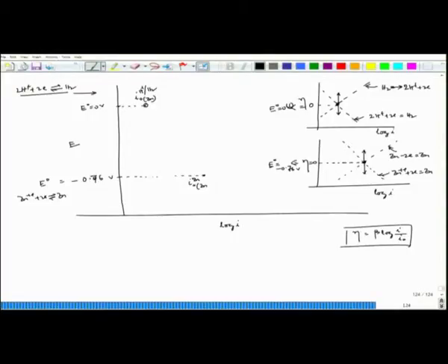When they do that, they follow their own anodic and cathodic polarization plots as per these equations. In the case of zinc, the polarization follows this line, and the polarization of the hydrogen reaction follows this line. Now they will meet somewhere here.